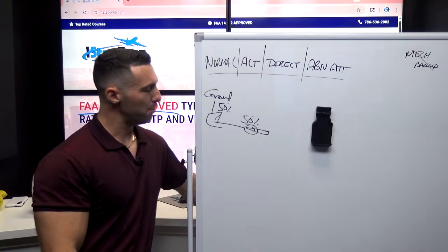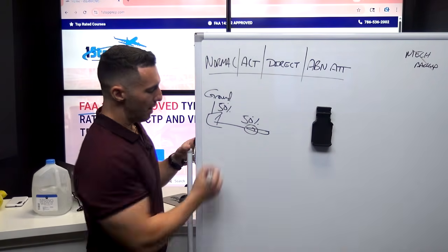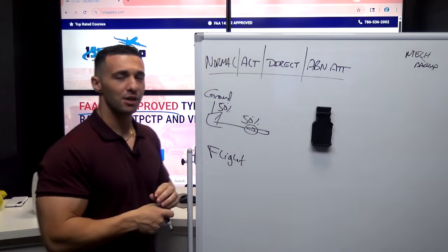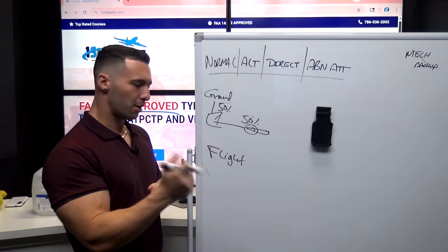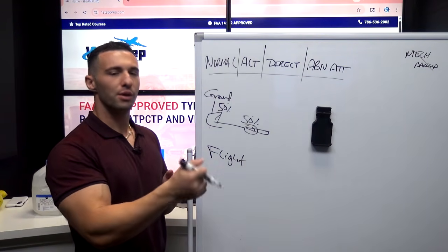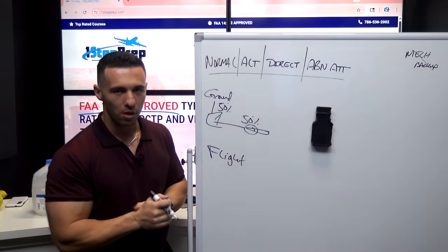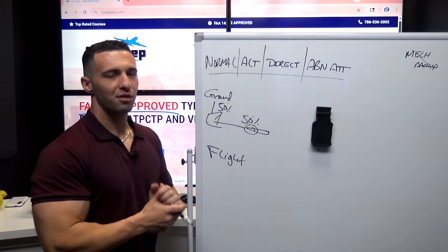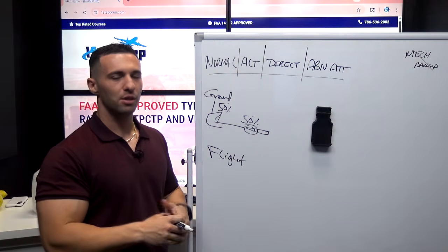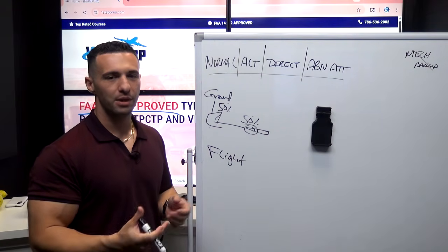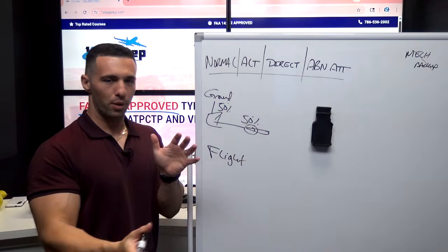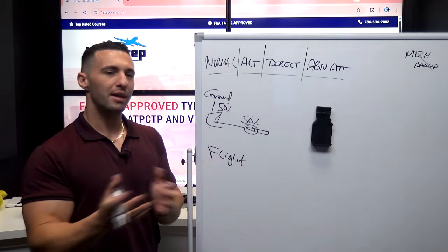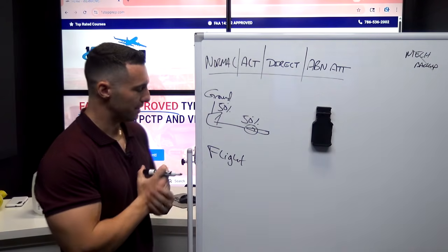And of course, from ground mode, now we transition to flight mode. Flight mode is basically where the side stick characteristics change, and we go from a direct communication to suddenly the G-load and the roll rate that you would expect in normal law in flight. The transition period is about 5 seconds. This is why the autopilot says don't engage it until approximately 5 seconds, 100 feet once we're airborne. It's going from ground mode to flight mode, as they like to call it, the blending. That blending process is the 5 second or 100-foot delay.